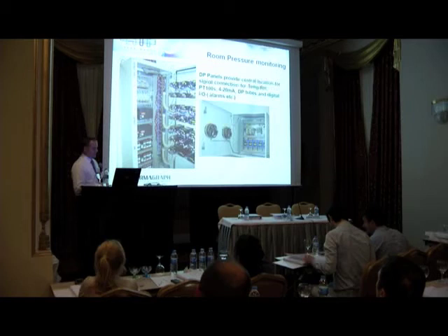As well as monitoring pressure, we can also monitor temperature and humidity. You can do that for rooms, obviously, and we now do a lot of monitoring inside incubators for biopharma applications and so forth, and sometimes inside isolators as well. We also have quite a high-end, just using PT100s, very accurate IO module which allows us to monitor temperature to about 0.1 degree accuracy. Most systems can only claim to monitor to about half a degree, but we can go that extra step.